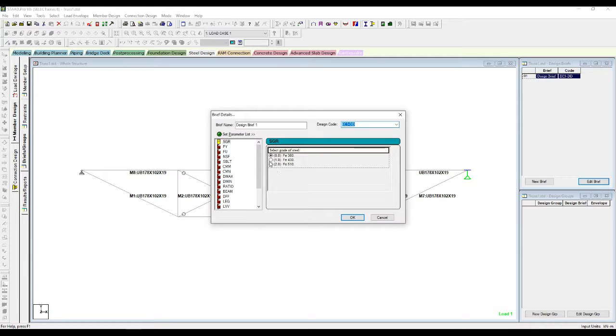In this case, I'm gonna be working with this kind of steel with ultimate capacity of 430 megapascals. So here in this window, I'm going to explain a little bit what happens here. So you can do a standard Eurocode 3 check, or if you are working with a national annex in your country, you are going to need to modify a couple of things.